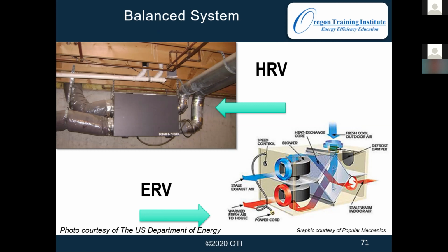Though we'll look at, I think I have a slide with some photos of one that's connected to a forced air furnace, which can work, but sometimes that might mean running your furnace fan to move the air, which is going to be a lot more expensive to run a furnace fan all year round. But the idea is not only to get the fresh air in, but to capture the heat that would have been wasted while maintaining the pressure in the house. So keeping it neutral where it's not being depressurized or overly pressurized.